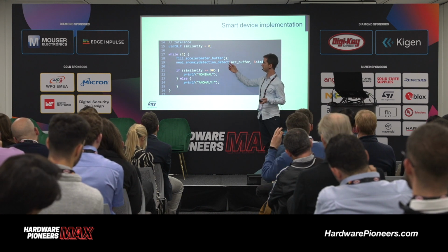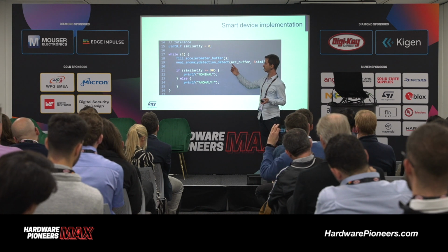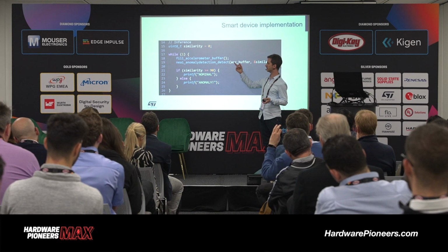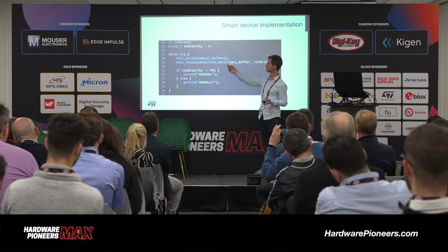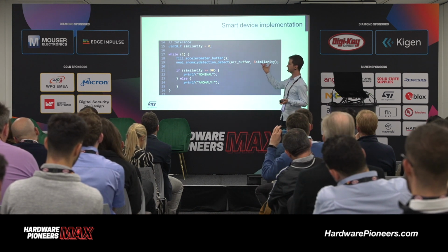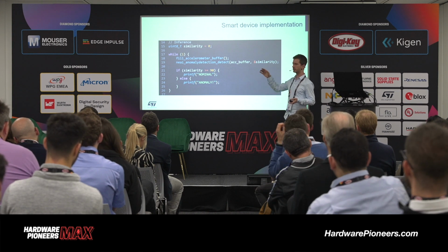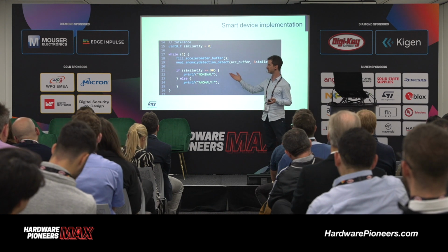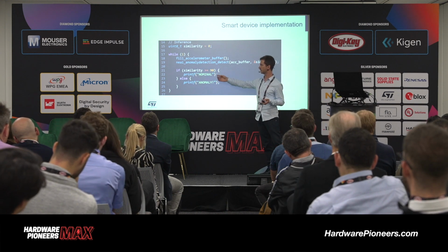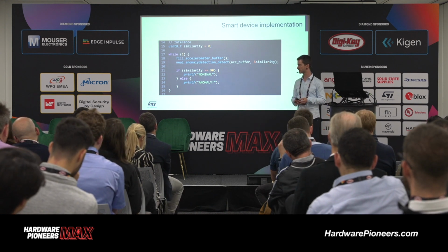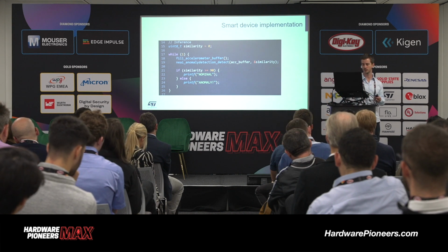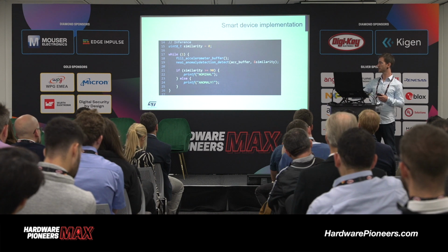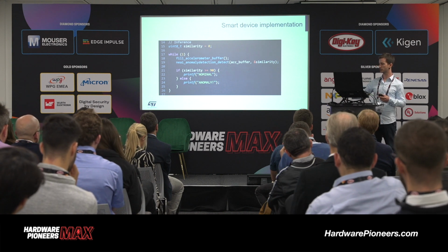You get fresh accelerometer data, and then instead of passing the accelerometer buffer into the learning function, now you pass it to the detect function, and the output is a similarity percentage, and you can place a threshold on the similarity to make decisions. So here, simple thing, we consider that above 90% it's normal, and under 90% it's abnormal. But again, it's a very simple example, and you could imagine some much more complicated logic.